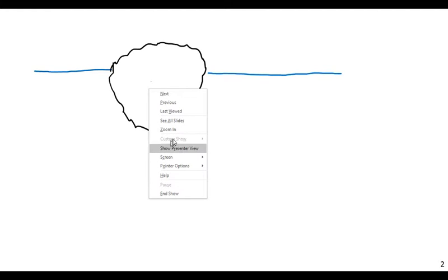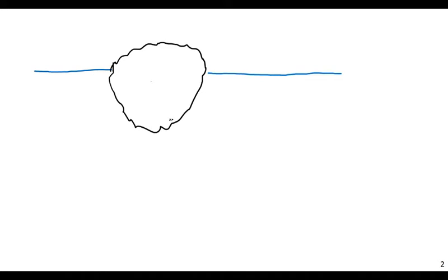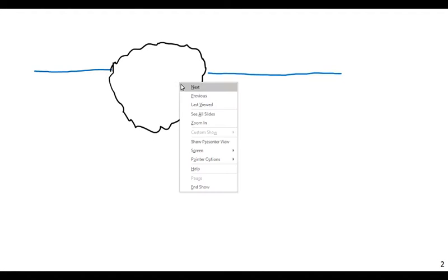Now, as we mentioned last time, the center of buoyancy of an object is going to be at the centroid of the volume of fluid displaced. Meanwhile, the center of mass of the object will be at the center of mass of that particular object. Now, for very simple shapes like a cylinder, these will inevitably line up, but for more complex shapes, like a ship, for instance, this need not actually be the case.